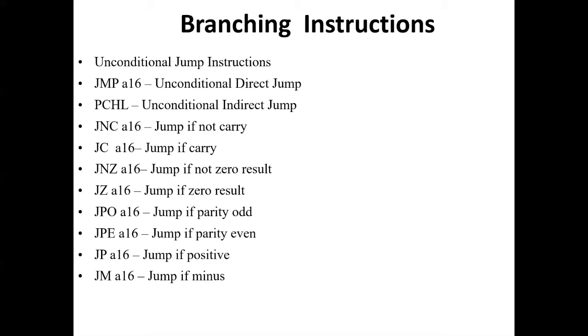Next is JP A16. JP is a mnemonic which stands for jump if positive. This instruction is used to jump to the address A16 provided in the instruction only if sign flag value is 0. If sign flag value is 1, the program flow continues sequentially.